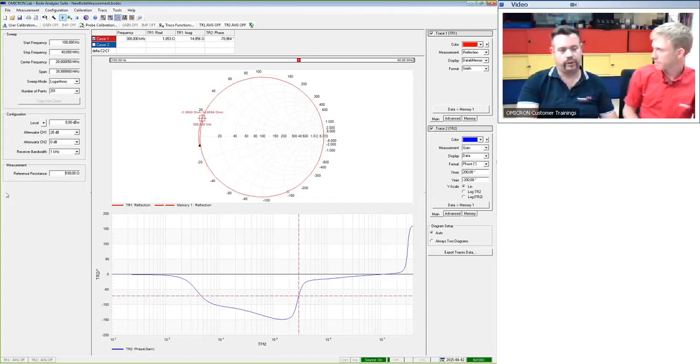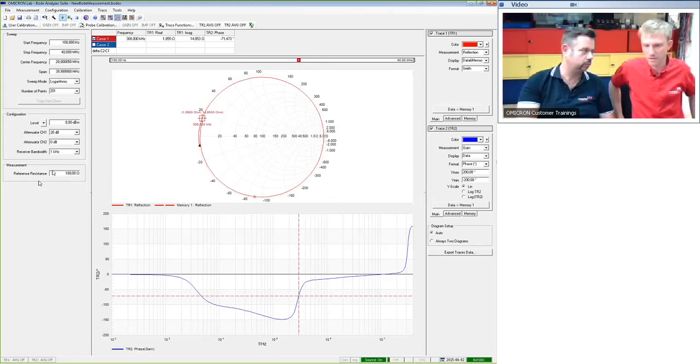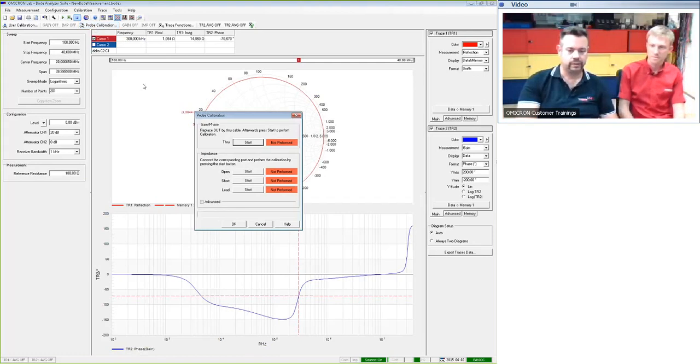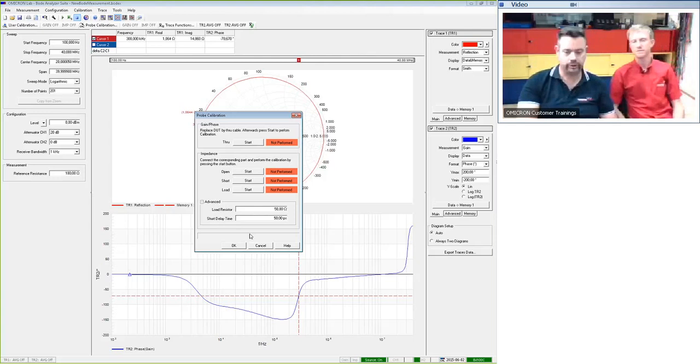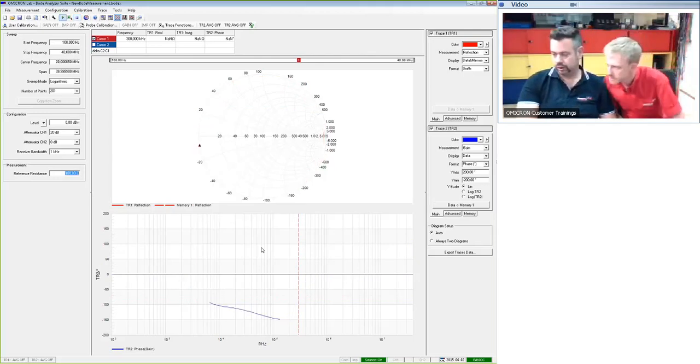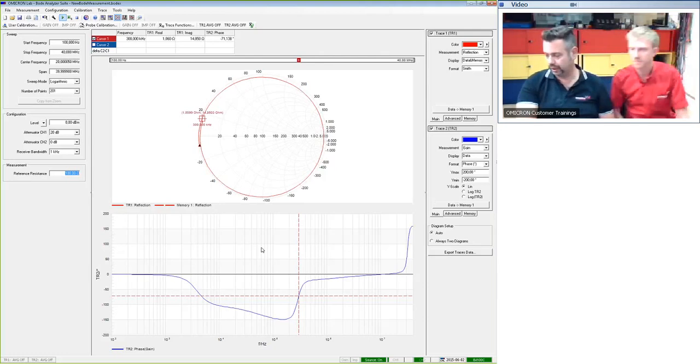And we already plan for a future release of the Bode 100 to make this more clear. So this is not the resistance that is used during calibration. If you do a full board calibration for impedance, then the reference resistance is put in here, and it's either 50 ohms if you are in the 50 ohm domain, or if you use our impedance adapter by design, it's 100 ohms, but you can enter values here if you don't have a 50 or 100 ohm resistor at hand for the calibration. So I hope that this answers the question.